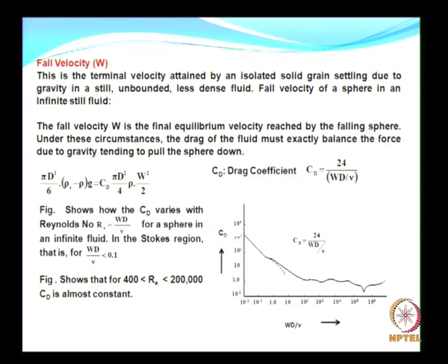So this figure shows how the coefficient of drag will vary with the Reynolds number. You brush up the fundamentals: when you talk about coefficient of drag, naturally it is associated with Reynolds number, and Reynolds number is nothing but Wd divided by nu, where nu is the kinematic viscosity, and we have also given the limit for the Reynolds number. Now if you look at this picture, this shows how the drag coefficient is going to vary with respect to the Reynolds number.